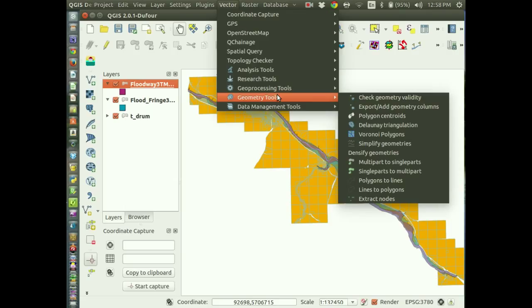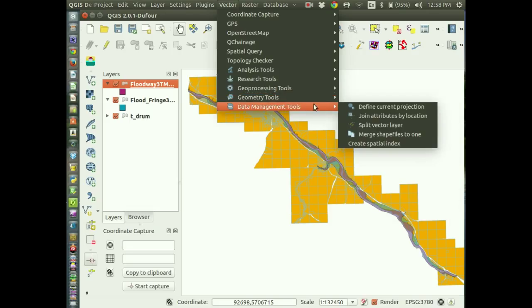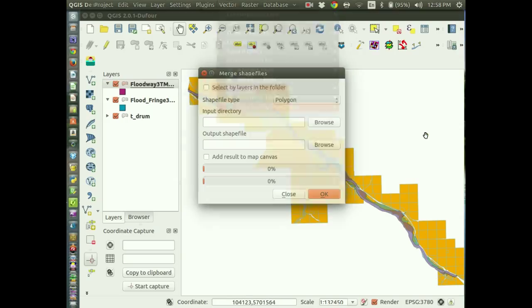Now the idea of why you want to merge these layers is just so you can have a base. You want to merge the floodway, flood fringe, and the overland flow area, the inundation area, into one polygon. Then you want a buffer. That's the outer bounds of your project area. Then you want to capture all the buildings inside that to make sure you've got the total inventory. Okay, so that's the process. And we may not be successful here to do this, but I'm kind of stubborn.